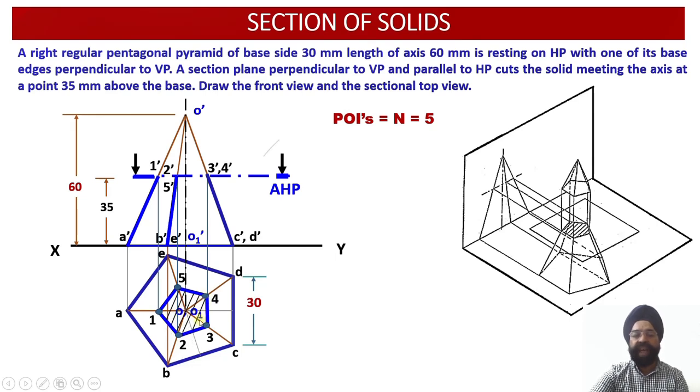So now in any case, sectioning has to be labeled with the help of hatching lines, and hatching lines are once again equi-spaced lighter lines which are drawn at an angle of 45 degrees with respect to the reference plane, which is our XY reference plane. So the intermediate reference plane is XY. These hatching lines will be drawn with a 2H pencil. These will be the equi-spaced lines at an angle of 45 degrees with respect to the XY reference line.